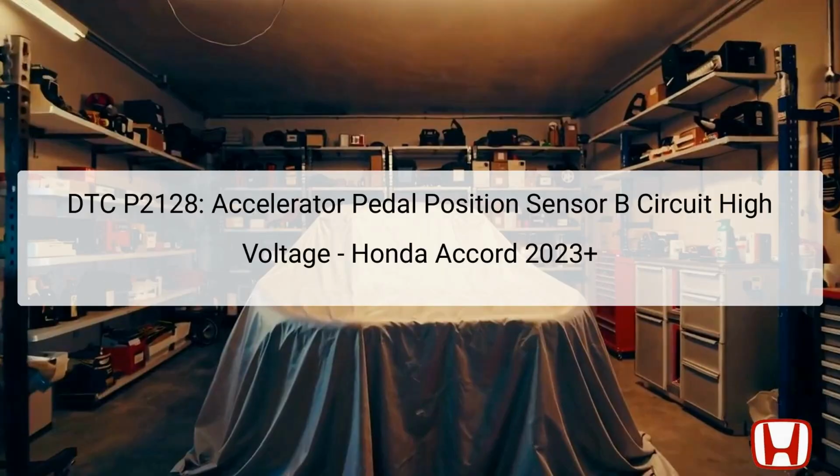The diagnostic trouble code, DTC P2128, indicates an issue related to the accelerator pedal position, APP sensor B. Specifically, this error arises when the output voltage of the APP sensor B exceeds a specified threshold, signaling an abnormality to the powertrain control module, PCM. The PCM is essential for managing engine performance and emissions, making its proper function critical.